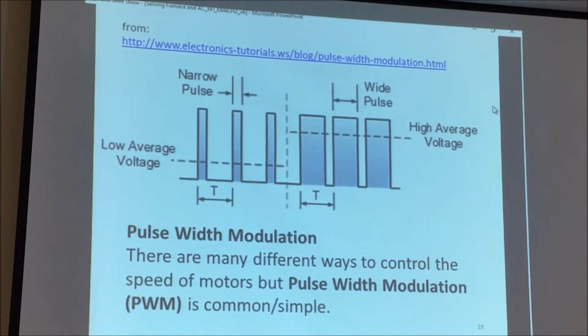And here is the gist of why this is problematic. The easiest way to have a commutatorless motor vary in speed is to generate a sequence of pulses of varying width. What's not shown here, but what we all know, is this is followed by a rectification and smoothing network. So if you have narrow pulses far apart, you have a low average voltage. Wide pulses, you have a high average voltage. After you smooth that out, you get a nice DC voltage, which drives the motors between 600 and 1200 RPM as a function of your heating and cooling requirements.